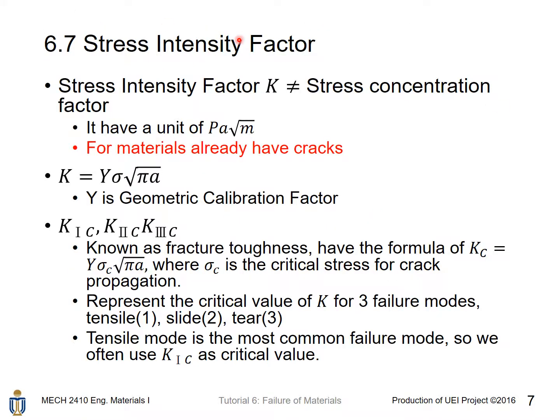Stress intensity factor. Stress intensity factor, K, is not equal to stress concentration factor. It has a unit of Pascal times square root meter. And it is applicable for materials already having small cracks within them. In real-life applications, nearly all materials already contain some cracks which are not visible to the naked eye. Therefore, we must consider stress intensity factor in the design of objects using these materials.